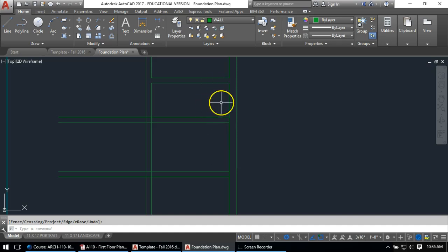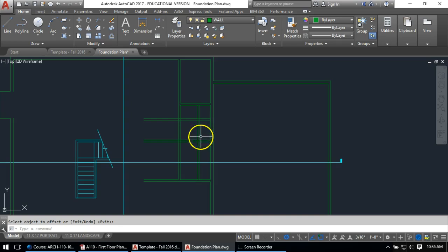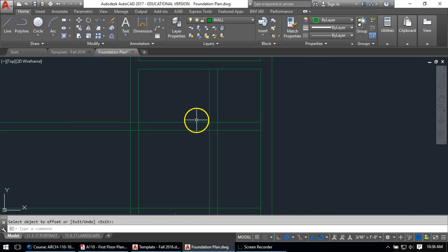But this is going to be a closet here. Most closets are 2 feet wide, so I'm going to offset 2 foot. And I'm going to do 2 foot clear because that's usually what you want closets to be. So I'm going to offset 2 foot from the wall. Then I'm going to offset the 4.5 inches for the wall. And I'm going to set the plane of this space. Now hopefully I have room for my 30-inch door and things like that. I think that I will.